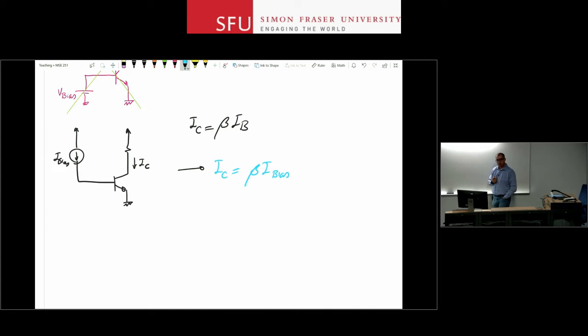Okay, so I hope you thought about this for a second. The problem that you have with this circuit is this fellow here. Beta is not a well-defined parameter. Even for a given transistor, you have checked the data sheet for your labs, and you notice that beta value changes with IC and temperature and all sorts of parameters, and also between device to device. So if you make 1,000 devices, 1,000 circuits, you have 1,000 values for beta.